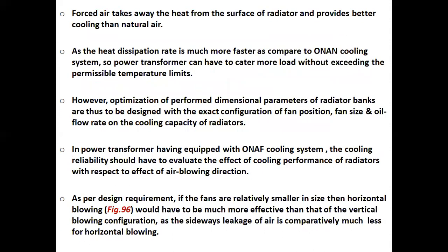Forced air takes away the heat from the surface of the radiator and provides better cooling than natural air. As the heat dissipation rate is much faster compared to ON type cooling, the power transformer can cater to more load without exceeding the permissible temperature limits. However, optimized dimensional parameters of radiator banks are to be designed with the exact configuration of fan position, fan size, and oil flow rate on the cooling capacity of radiators.